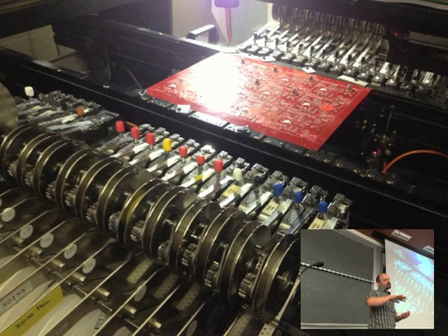Now, of course, if you have 2 layers, it's a whole different story. Because you put the parts on one side, right? If you put them through the oven, great, that will work. But how do you now put stuff on the bottom of your PCB, right? And they actually do that at the same time, and how they do it is with glue. So they first put a little bit of glue down, and then put the parts on top of it so that glue will keep them.